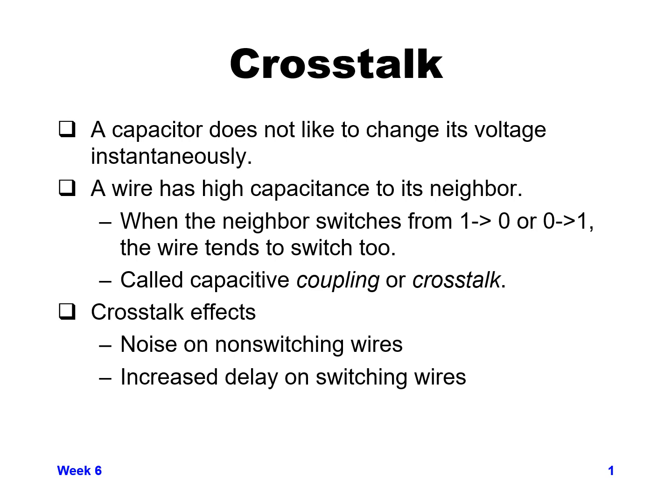The other thing it can do is, if you have a neighboring wire where one wire was supposed to switch from 1 to 0, and the neighboring wire was supposed to switch from 0 to 1, both at the same time, because they're capacitively coupling on each other, the effective capacitance looks like it's doubling, because the neighboring wire isn't stable. It's actually going in the opposite direction, and it will cause increased delay on wires that are next to each other and switching in opposite directions.